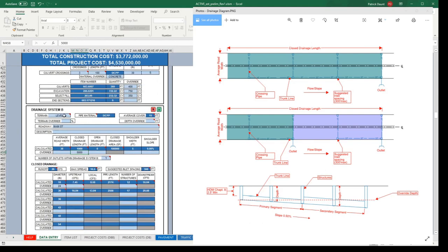I'm going to quickly change the level just to show you. So say Main Street isn't level. Say it's rolling. The rolling is going to change two things here. It's going to change the spread calculation because of that longitudinal slope. It's also going to steepen the pipe capacity because theoretically, if you're in rolling terrain, you don't need to run at a minimum pitch. You might be able to run at 1% or more, depending on, without busting through grade or making your excavation unnecessarily deep. So we're going to go with rolling.